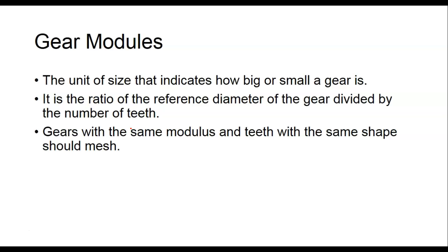The gear modulus. So what we got is different size gears, and when they mesh, of course, we got to have one gear tooth that engages and goes into the slot of the other. But the gears themselves can be different sizes. So if these gears are going to mesh correctly, the size of the teeth has to be the same, right? You understand that? As far as the depth. Sometimes, by the way, they'll clip off this little end because it doesn't do any work, and it makes the tooth smoother as far as transitioning in.